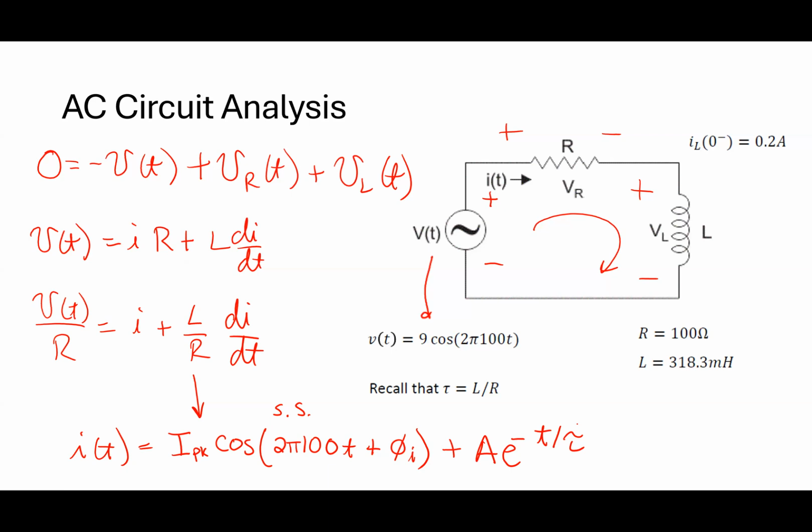And in this case, how does this go away? Well, if I wait longer, e to the negative t over tau, the longer I wait, what happens to e to the negative t over tau? It approaches zero, right? That should become zero. So this is my transient. Now, without getting into this, what is that going to make the current look like?